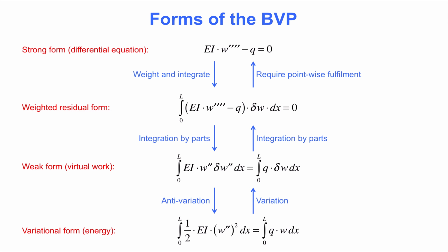It is a valid form, but it is also a weaker form than the differential equation. We no longer require pointwise satisfaction of equilibrium, material law, and kinematic compatibility. Rather, we now require the differential equation to be satisfied in an integrated sense.